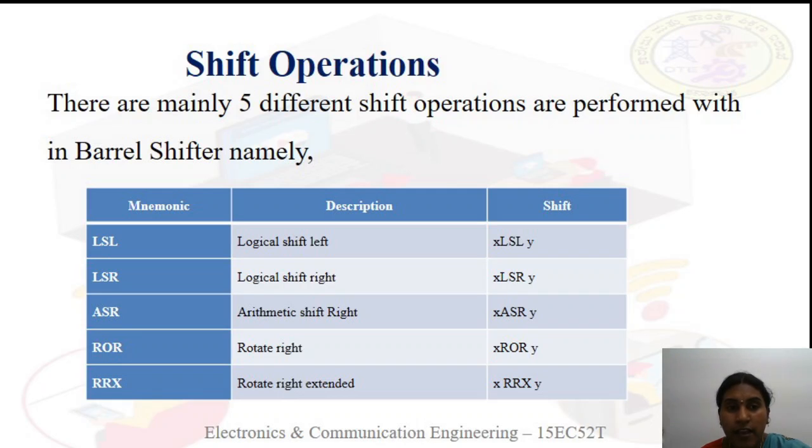There are mainly 5 different shift operations: LSL, logical shift left; LSR, logical shift right; ASR, arithmetic shift right; ROR, rotate right; and RRX, rotate right extended.